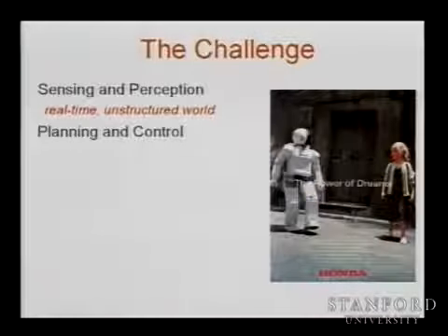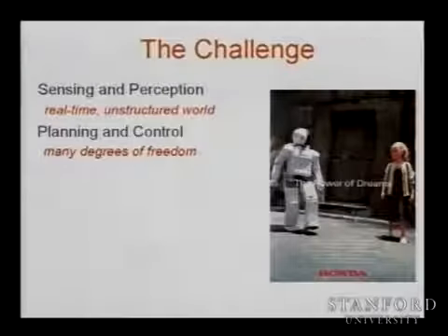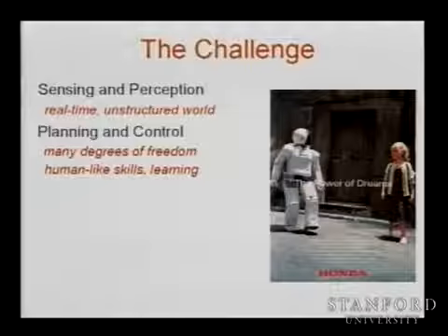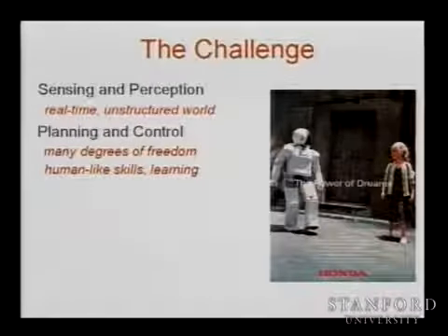Well, I mean, in the planning, the world is changing all the time, and maybe something else you wanted to mention? Multiple inverse kinematic solutions. Well, the number of degrees of freedom. You have a robot with not 6, 5 anymore. You're talking about many degrees of freedom, and you need to resolve and respond in real time. And you need in those machines to have not just move to a position. You need skills, almost human-like skills. So you are demanding much more.